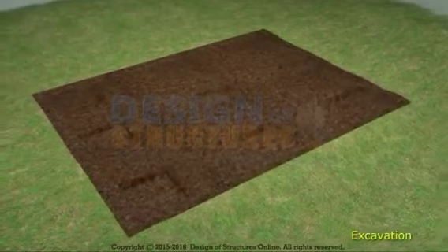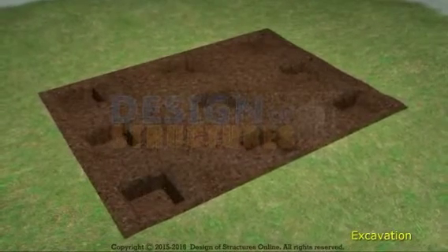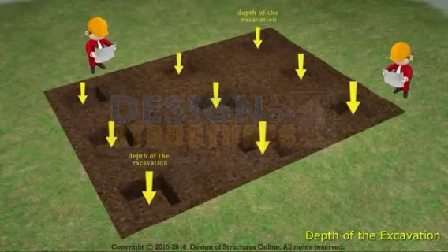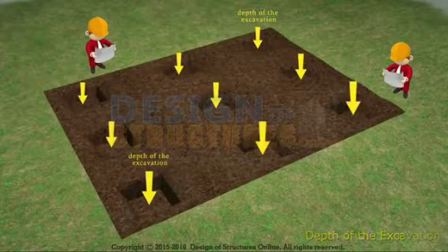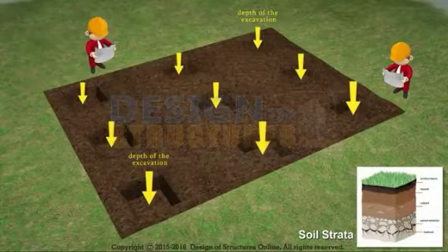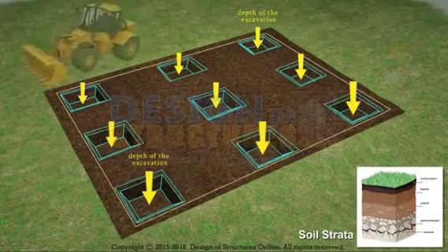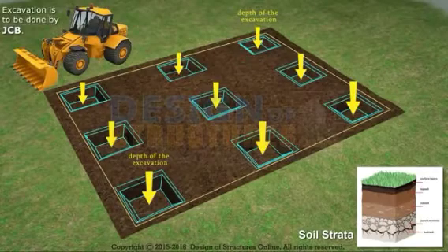Excavation. A structural engineer will be needed to determine the depth of the excavation. The depth will vary from building to building depending upon soil strata. Excavation should be carried out as per the drawings' defined lengths and widths. Excavation is to be done by the JCB.